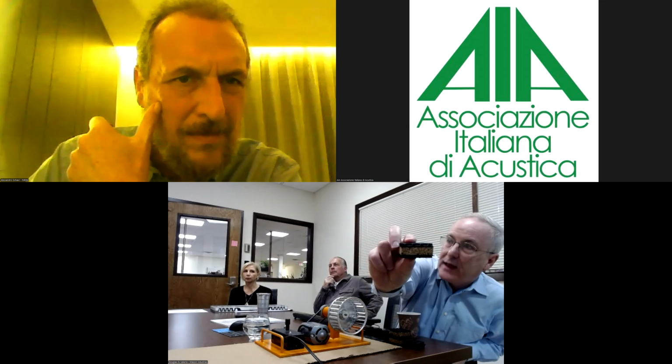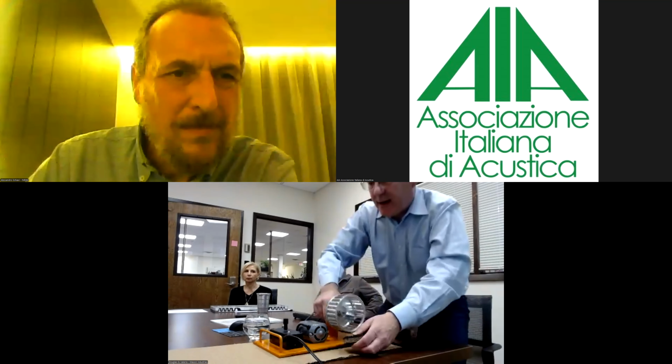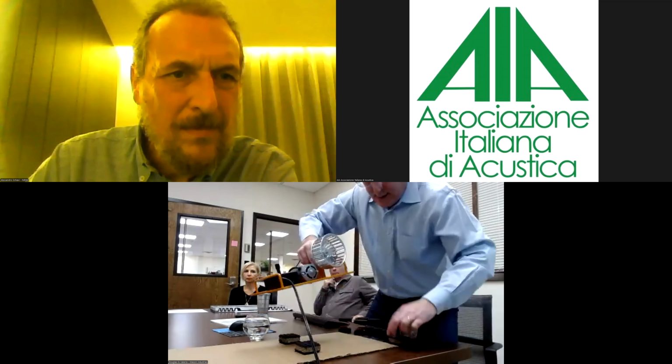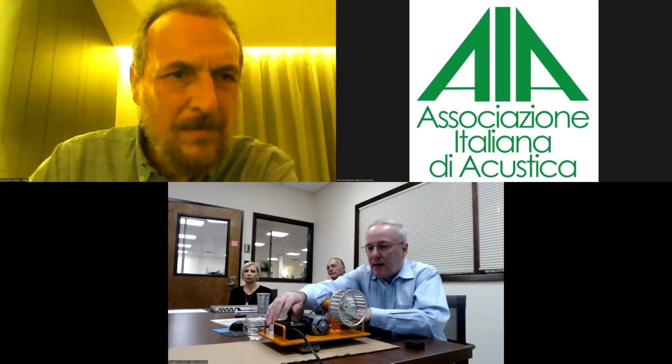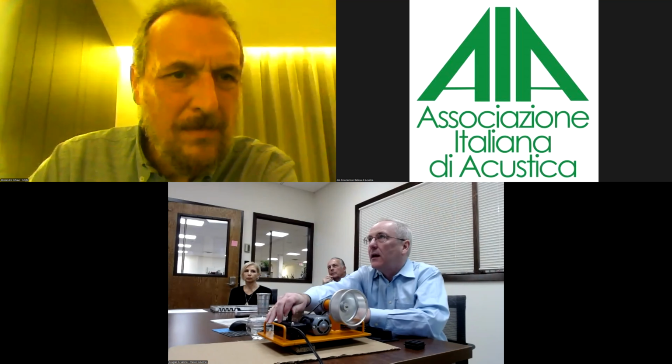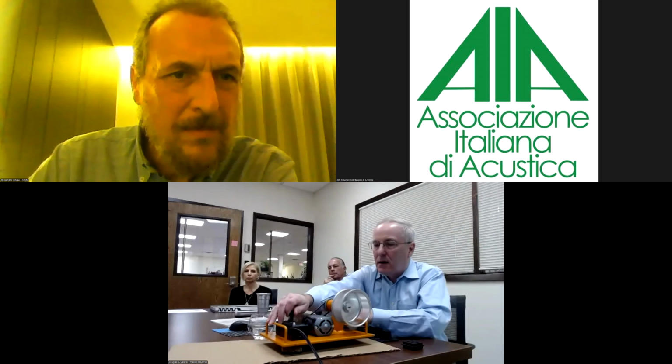So if we go through the isolators, one of the earliest isolators was a cork pad, very limited deflection. The close-up of that little cork sandwich. So if I take my machine and I place it on the cork, because it has a very limited deflection, the performance is not particularly great. You can see that. And of course, the pads are underloaded. The test is kind of rigged in my favor a little bit. Almost 100% transmission.